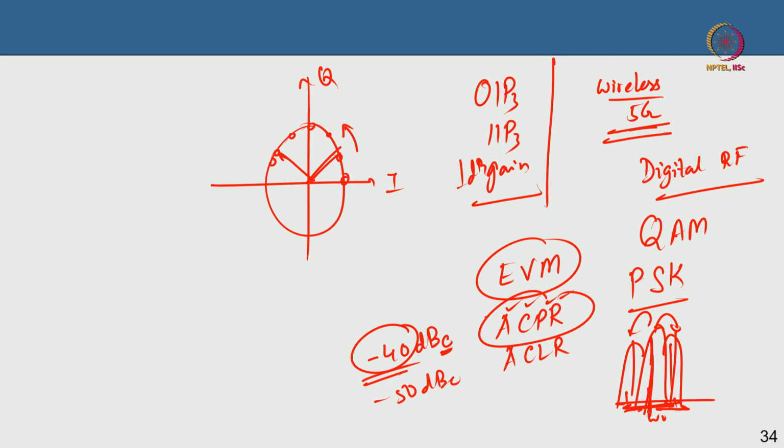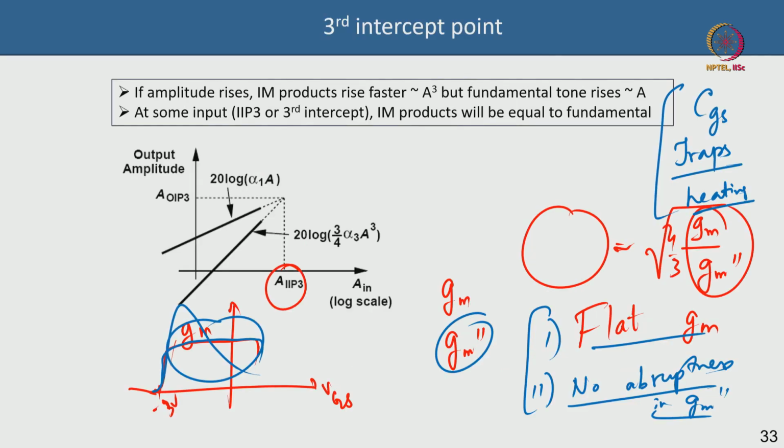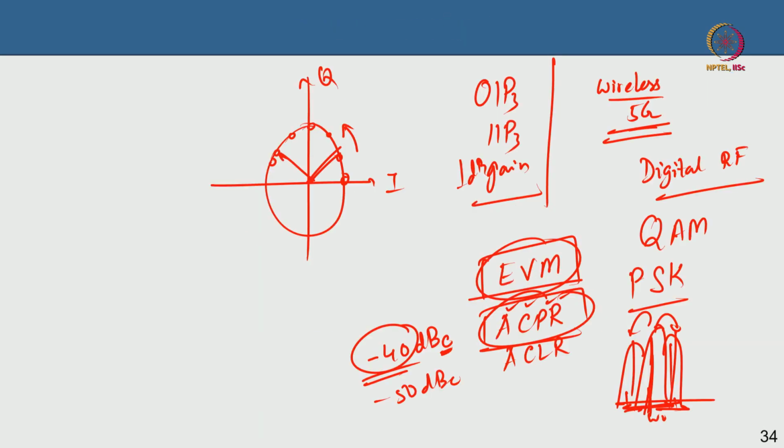So adjacent channel power ratio and error vector magnitude are some of the terms in which the systems people talk. The paper I had shown you here, the schematic here, basically found that the device level linearity metrics need not necessarily translate to an improved error vector magnitude or adjacent channel power ratio at the system level. But I am sure more studies are required in this direction in terms of experimentally validating the same and understanding different nuances, because many of these things like EVM or ACPR are actually derived or studied once the device is put into the particular environment.